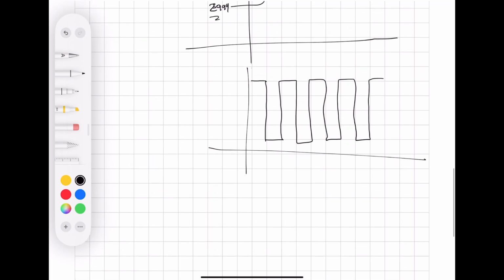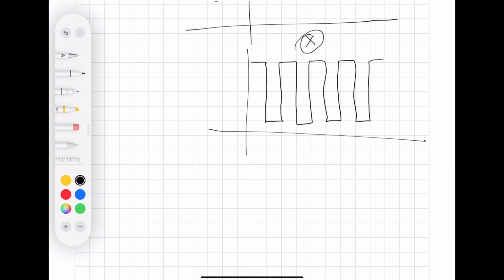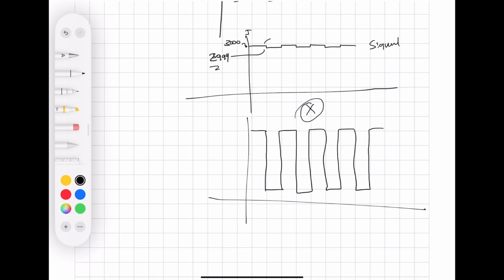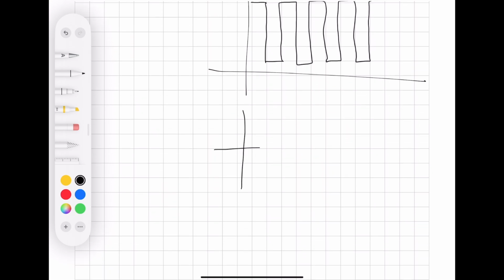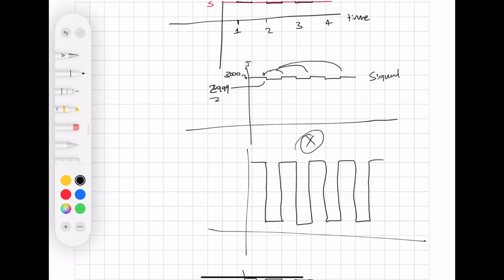I won't go into the details of how the signal and the reference are mixed, but maybe in the future we'll go into the details. For now, what I want you to know is these two are mixed such that the signal at this frequency is amplified. So we're going to have an updated signal with the same frequency, but much lower noise, or you can resolve the signal better. Initially what we were measuring was this, and we were very unsure of what the actual photocurrent was, because it's hard to subtract these two.